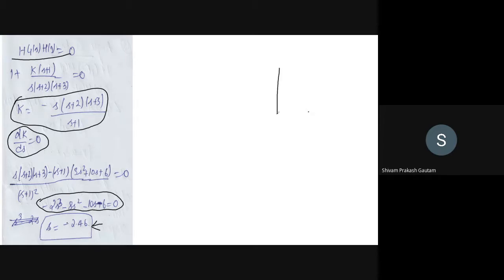Now out of those 3 roots, you have to see which root is satisfying our present root locus condition. So let me again draw the root locus here. One pole is here, another zero is here, one is here, one is here. So this is -2, I think this is -3, this is -1, and this is 0.